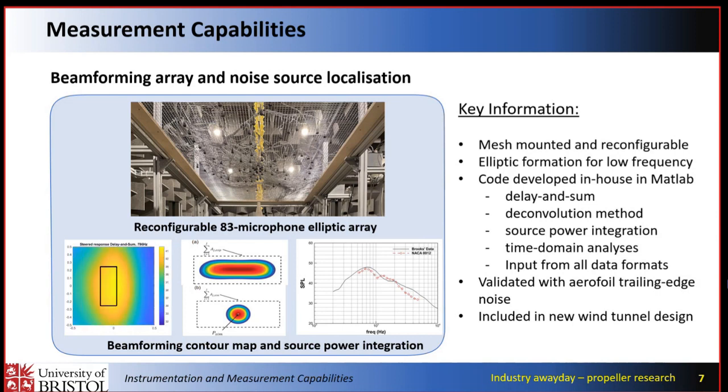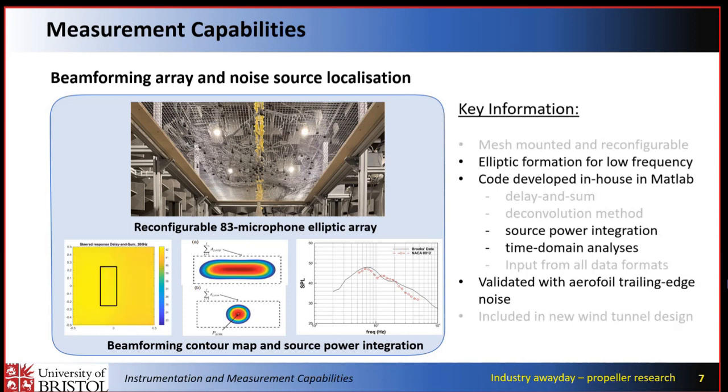If there are any noise components, or any airframe propeller interaction, then we are interested in finding out where exactly the airframe produces noise. Then we make use of beamforming array studies, where at Bristol we have spent quite a fair bit of time developing the techniques in-house. This is one of my pet topics. For instance, here on top of the slide is an 83-microphone reconfigurable beamforming array, meaning that the microphones can be connected and disconnected in locations where we designed them to be.